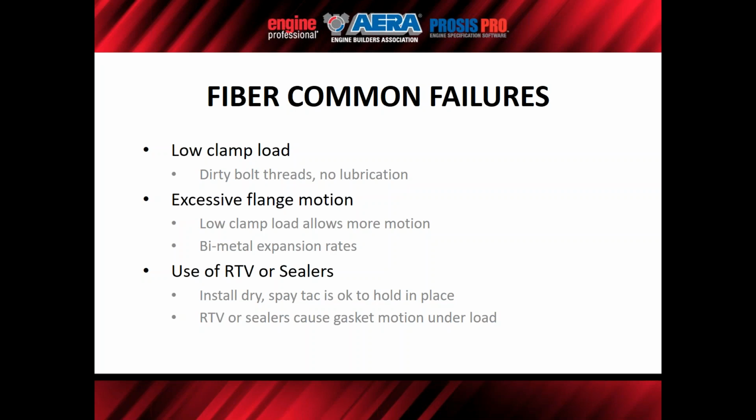So, use of RTV or sealers. All right. Again, I explained earlier, some guys like to goop up the surface of the gasket with RTV, and some people are successful with it. Some people are not. So, if you're successful with it, I don't want to say you're doing it wrong, but, you know, we don't recommend it. And I can see I got a typo there. Install dry. It's spray tack, not spay tack. It is okay to hold the gasket in place.